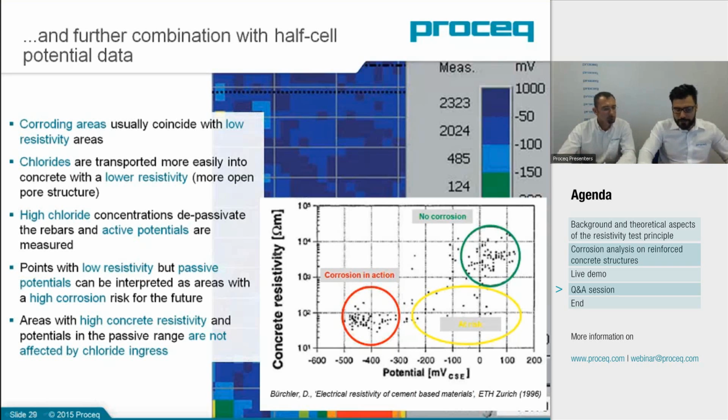Now, what influence does cracking on the surface of the concrete have on resistivity measurements? Well, it gives apparent high values. So resistivity is not an established method for cracking investigation. It is affected by cracking, and you don't want to measure over cracks. As far as I know, there is no systematic experimental work for estimating crack depth with resistivity.